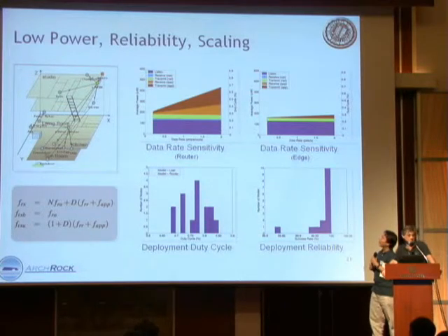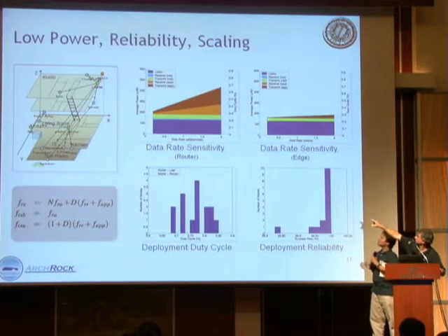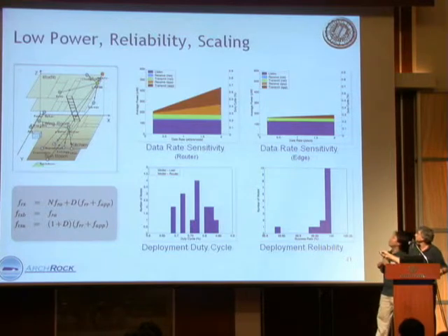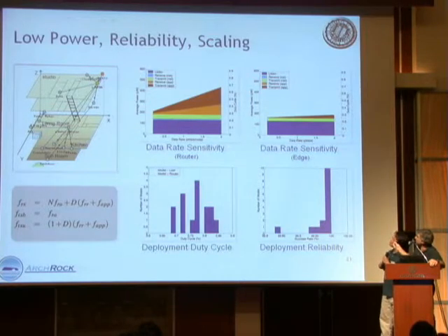This is the network in my house in Berkeley, my study in the corner. The thing to observe here as an example, low power. This has been running for a year and a half. The power is 200 microwatts on average. And if we were sending very frequently, so that here we see the duty cycle of the nodes, 0.5% of the time are they on. Or for many of the nodes, 0.25%.